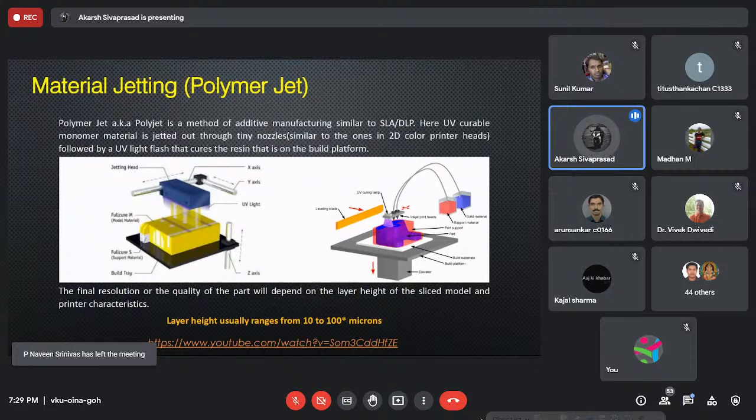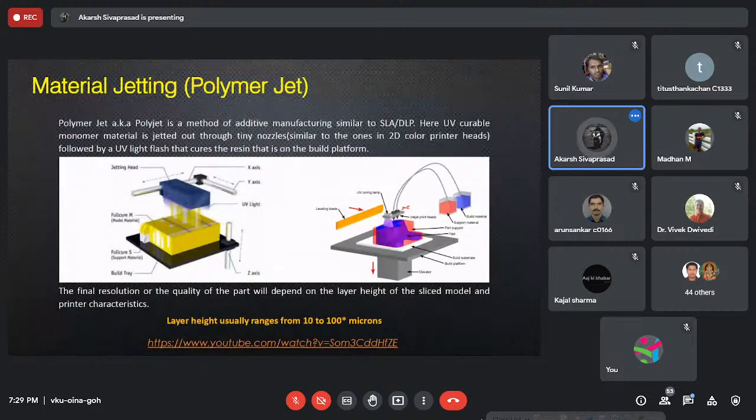Overhangs are surfaces which don't have supports or a substrate below them to support the next layer coming on it. Now that you have configurable 4-channel jetting, you can mix and match the support material to wherever you want, and then you get a final part.